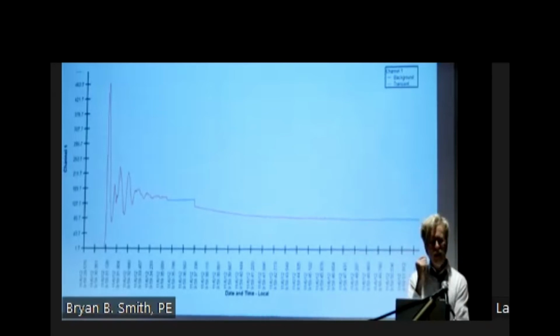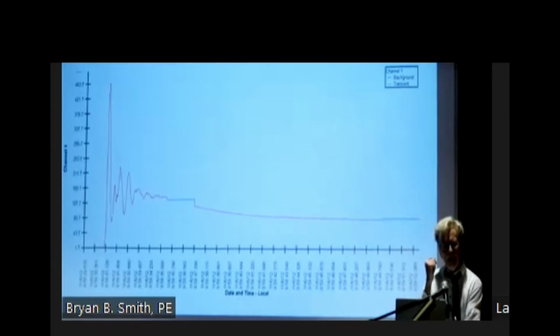Like, what do you mean? I'm like, your left-hand side of this pump curve, it's going to be 950 PSI when you start up this pump. They're like, what do you mean? I'm like, look at the pump curve. This is a vertical turbine pump.